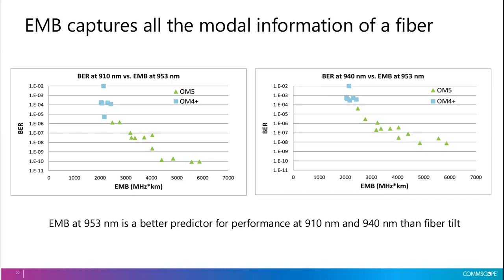Oh, that's a good question. So really it comes down to cost and length, and it's going to depend on each end user what they need. If you're having a data center, what links do you need? If your links are short, and you use this BiDi or SWDM4, your OM3 or OM4 fiber might still work. You have to look at your losses and your reaches that you have. But if you need that extra reach, then you're going to need to go to OM5.